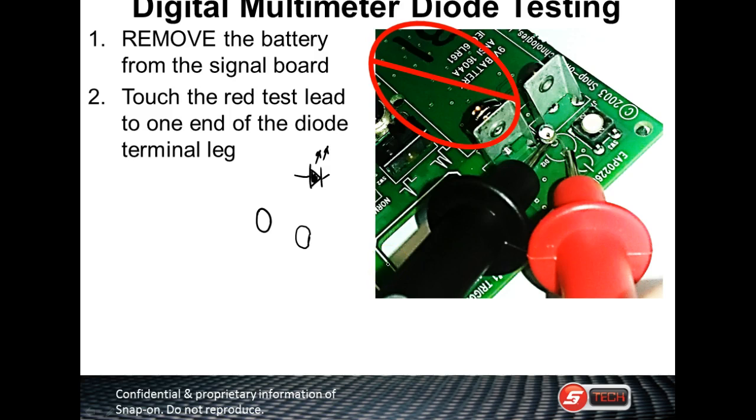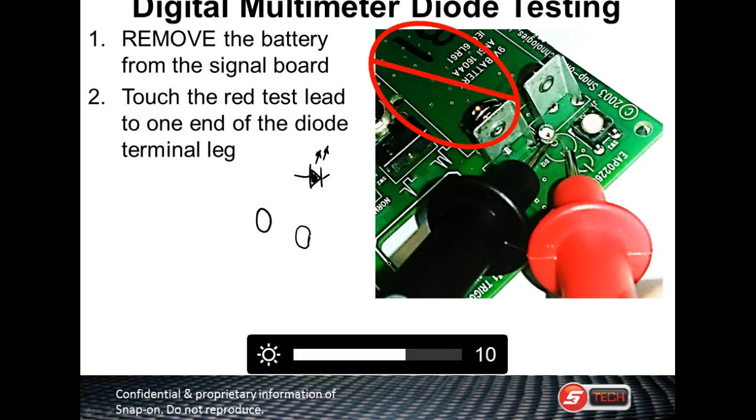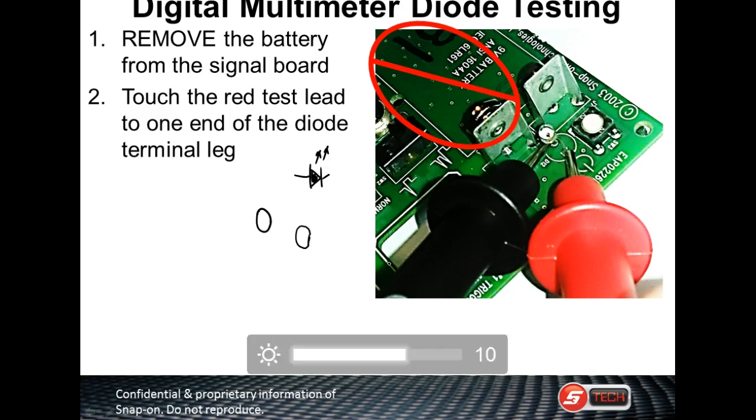So what do we measure? Hopefully not 0.7 on the LED. It should be 0.7 on a regular diode. Yeah, 1.5. Rule of thumb is around 2 volts for an LED. So that's perfect, right? This meter, my Sperry, doesn't put out enough current to turn the LED on. So this will only work with some meters. You can't check LEDs with all meters.